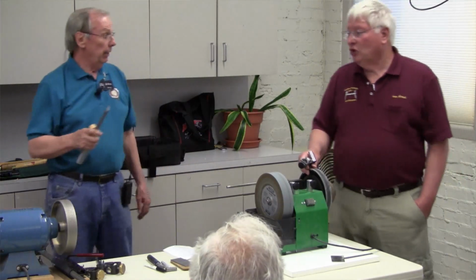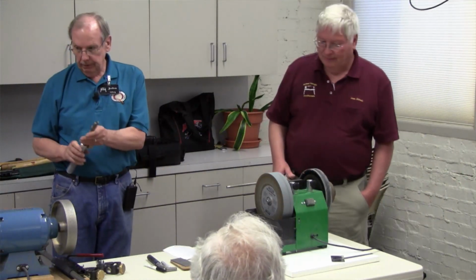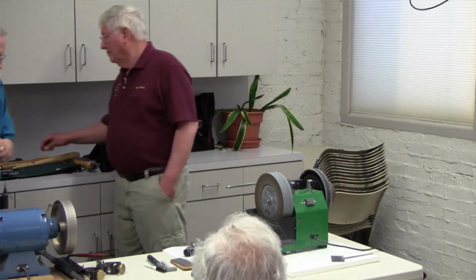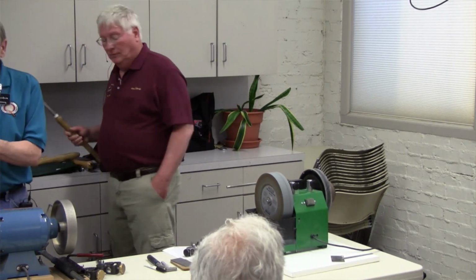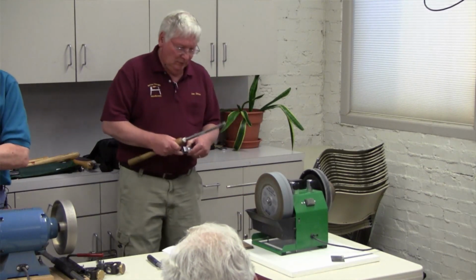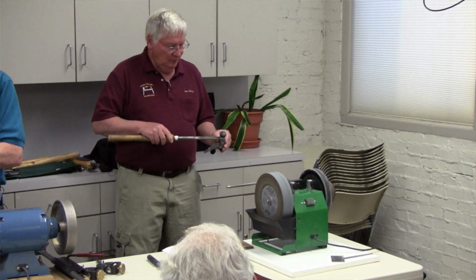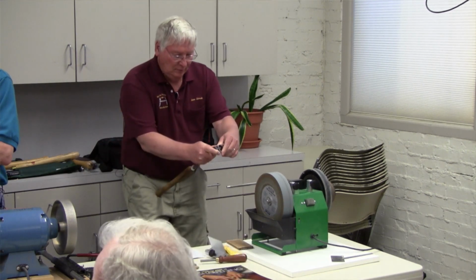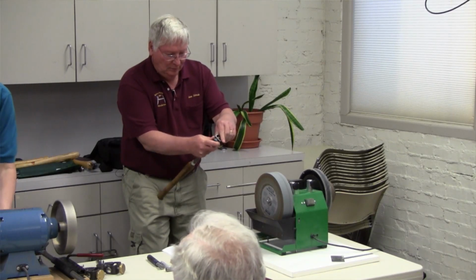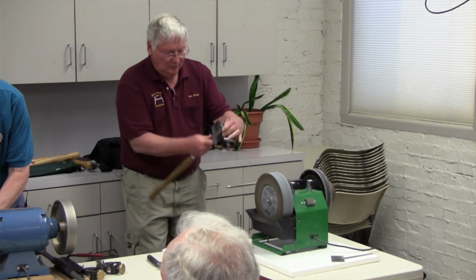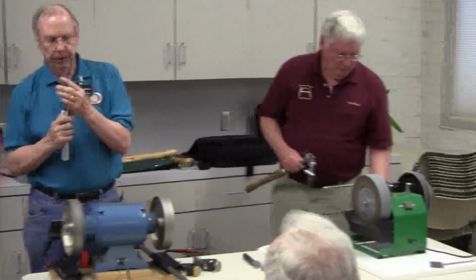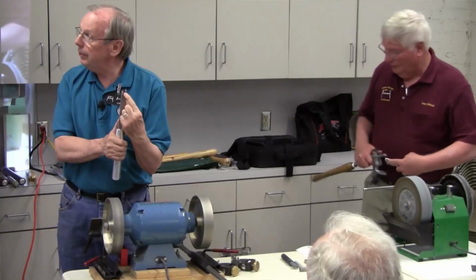Should we demonstrate? Sure. I'm going to demonstrate sharpening my skew, and Sam will set up and do a tool. One of the nice ways, if you're just starting out and you're comfortable with the angle of your tools, is to take a magic marker and add it to the edge, so when you go up to your grinder, you can find the spot where you're grinding, and you can see on this one, I don't know if you can see it,